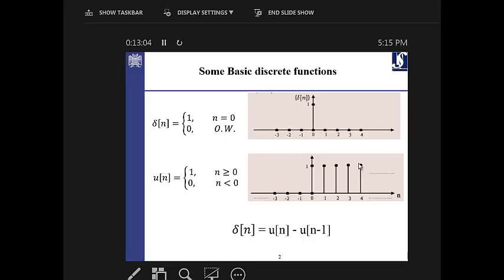So we have the signals and functions. Frequently I'm using the concept of signal or the concept of function, it doesn't matter. They are representing the same thing here in the discrete domain. So the first function is actually the unit impulse. The unit impulse is defined as a value of 1 taken at the origin, which is 0, or the time 0, for example, and 0 everywhere else.